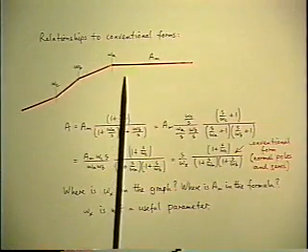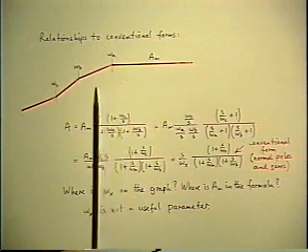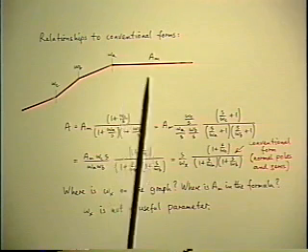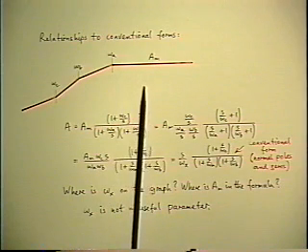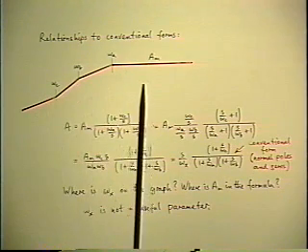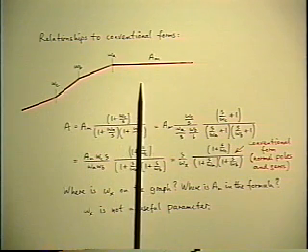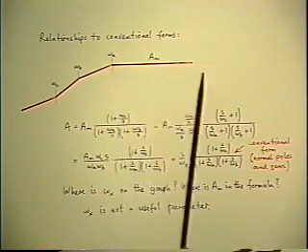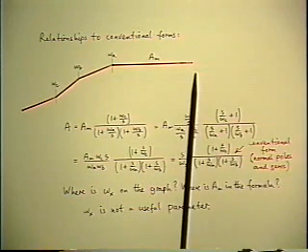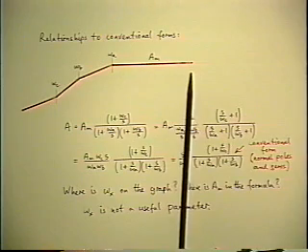In fact, this is one that we already had in examining the relationships that are involved with inverted poles and zeros. What I have recommended is that if you want to write the factored pole zero form for this sketch of the magnitude asymptotes, in which there is one flat gain, presumably the flat gain is the single most important parameter that you need in the result.